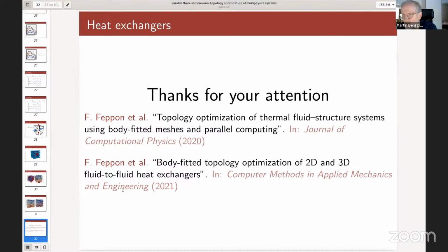But since the topology changes and everything, could you give fixed parameters for that, or do you...? Yes. You give parameters to the remeshing tools. At every iteration you remesh your structure, and the MMG library will impose the edge size that you want on different boundaries of the domain, which are represented by fixed numbers. Okay.